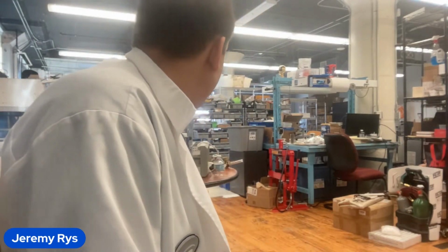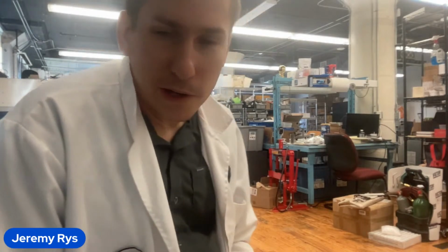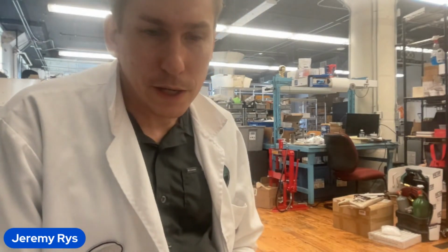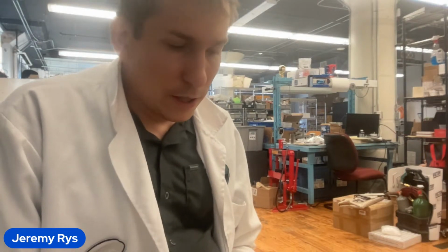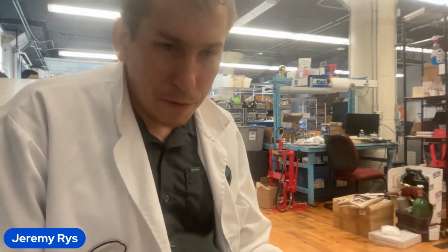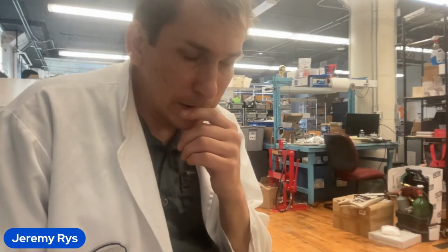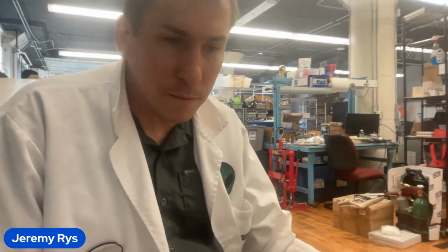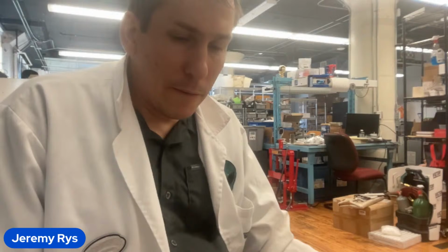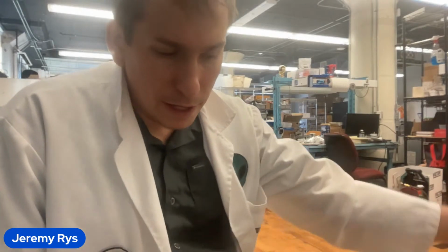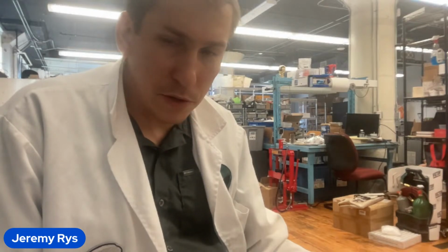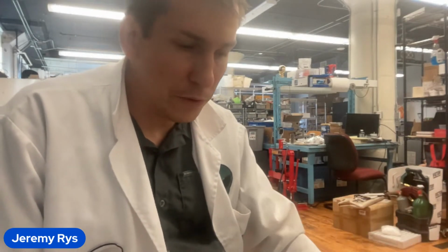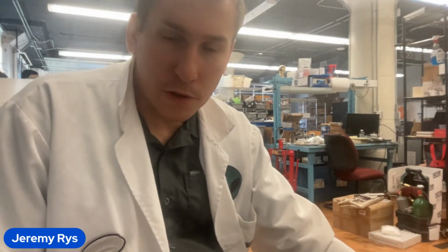We got the bismuth nanoparticles. I showed you that. We're trying to make the bismuth magnesium layered materials. The best thing we could come up with is this 3% zinc magnesium alloy, which matches their layer pretty well, and then we chemically deposited the bismuth onto the magnesium with bismuth chloride and electrochemically plating it.